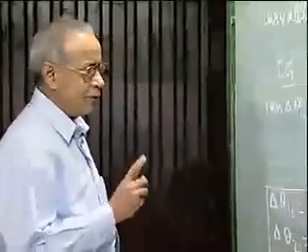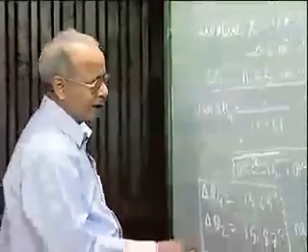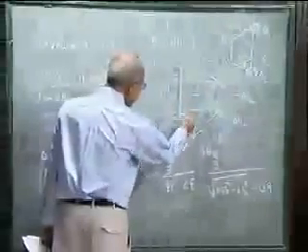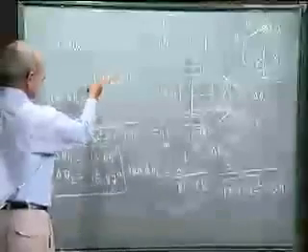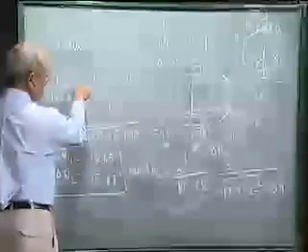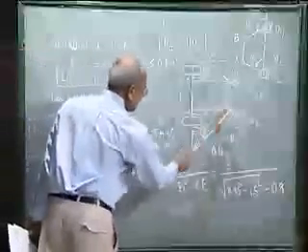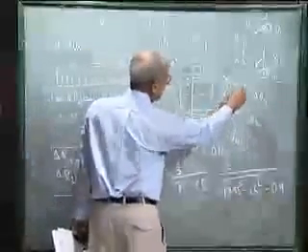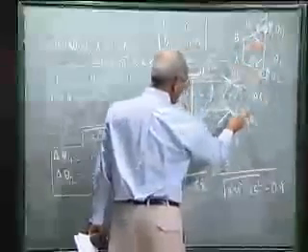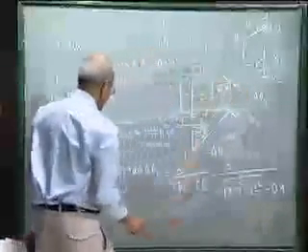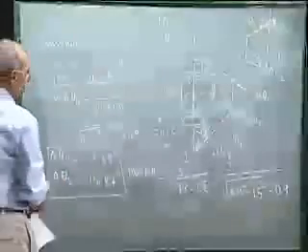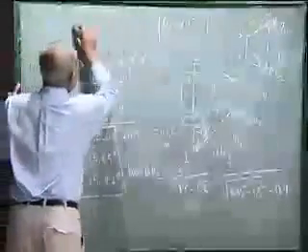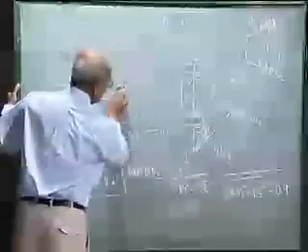So we see that if we want to satisfy the perfect steering condition corresponding to the radius of curvature of this point G for 11.55 meter, that is a little higher than the minimum value of 10 meters. This is our accuracy point where the steering condition will be perfectly satisfied, that these two wheels from this neutral position will rotate by delta theta 2 and delta theta 4, which are given by 13.65 and 15.87 degrees. So we get a second pair of coordinated values for theta 2 and theta 4.